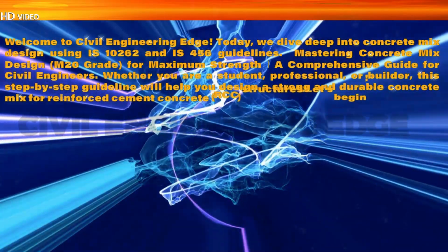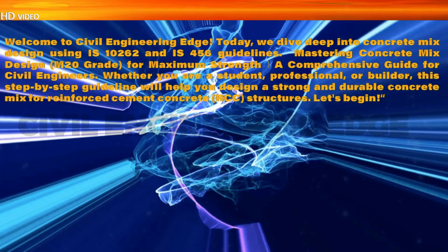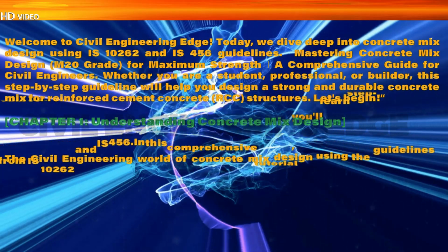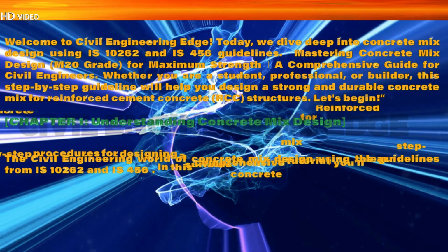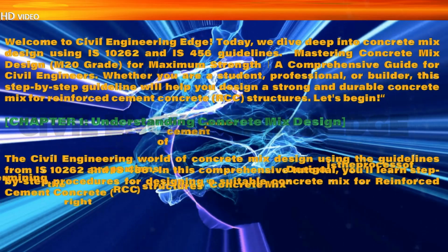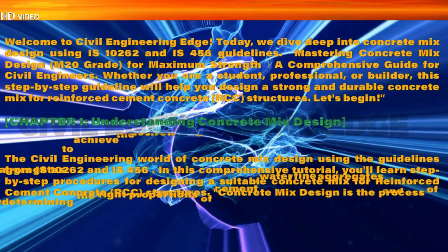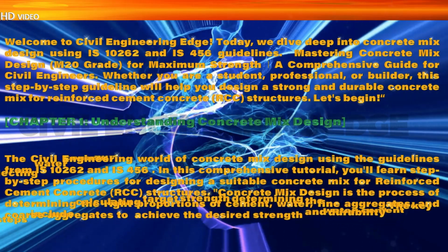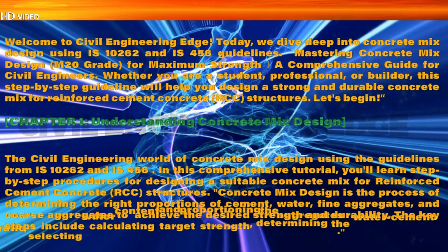Let's begin. Chapter 1. Understanding Concrete Mix Design. The civil engineering world of concrete mix design, using the guidelines from Indian Standard 10262 and Indian Standard 456. In this comprehensive tutorial, you'll learn step-by-step procedures for designing a suitable concrete mix for reinforced cement concrete, RCC, structures. Concrete mix design is the process of determining the right proportions of cement, water, fine aggregates, and coarse aggregates to achieve the desired strength and durability.